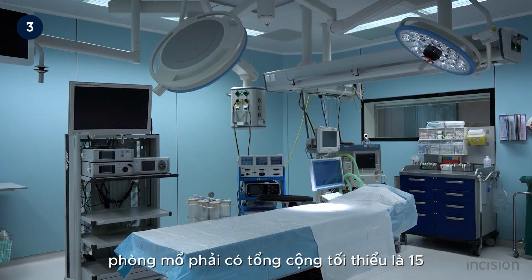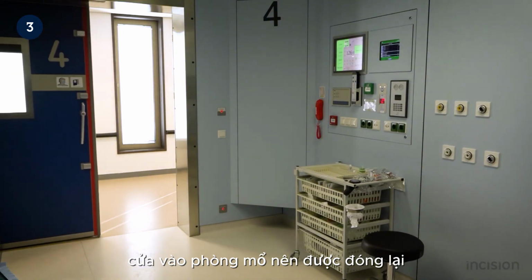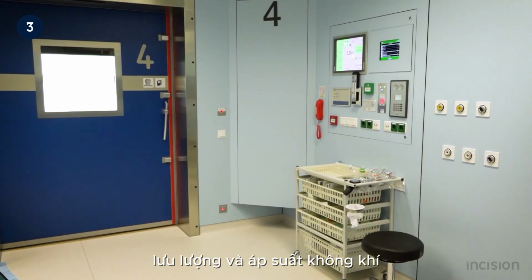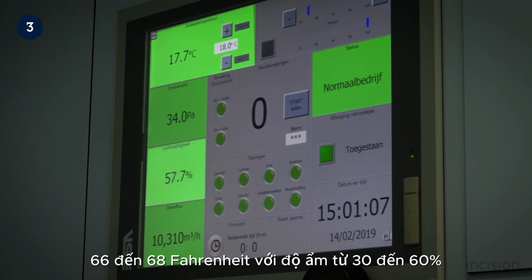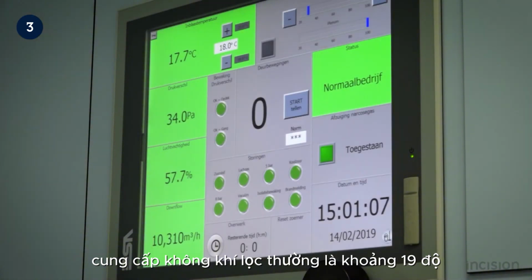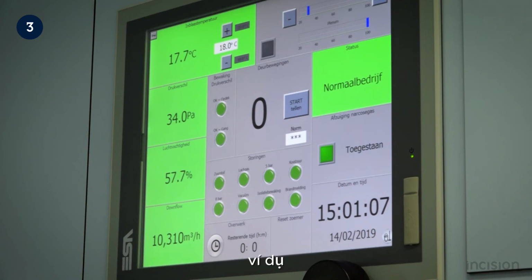The operating room should have a minimum of 15 total air exchanges per hour. Doors to the operating room should be kept closed in order to maintain correct ventilation, airflow, and pressure. The temperature within an operating room should be kept between 18 and 20 degrees, 66 to 68 Fahrenheit, with humidity between 30 to 60%. Supplied filtered air is usually around 19 degrees, but can be adjusted if necessary. For example, higher temperatures are preferred for children since children's bodies' heat decreases more quickly.